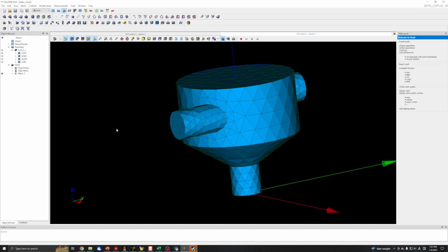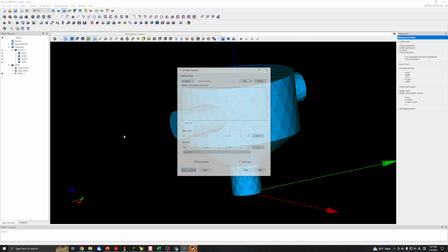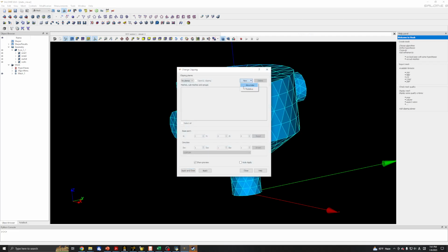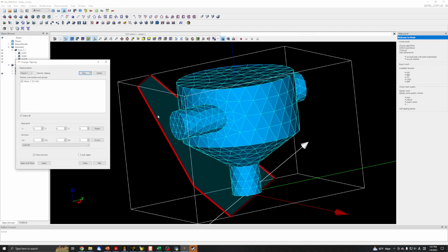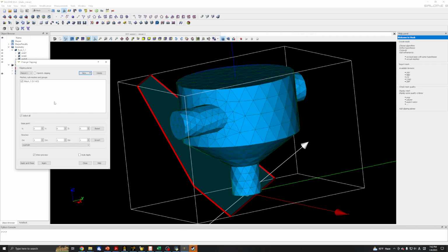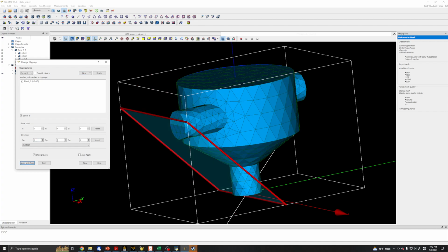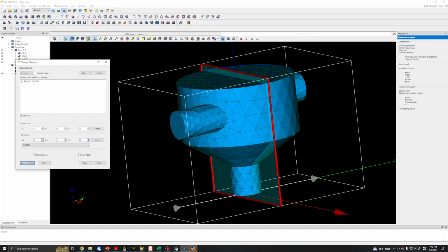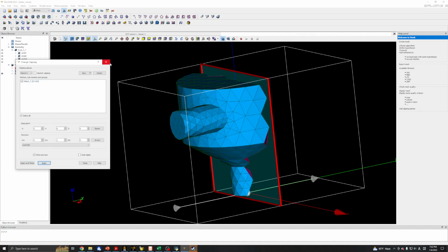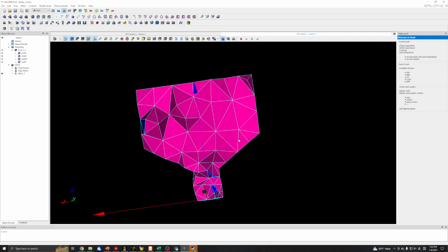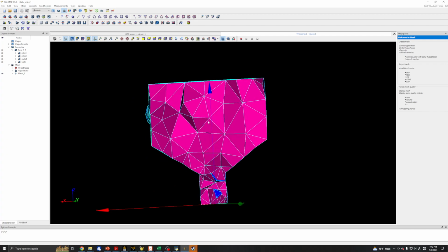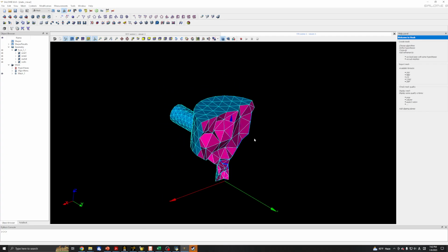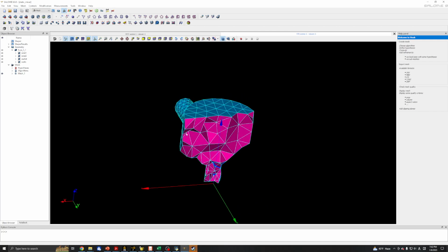First, right click on the main window and choose clipping. Then we can choose new absolute. Now we have our plane through which this mesh will be divided. The direction I want is the y direction, so all we need is to make dx and dz 0 and apply. Oops, it's too big, right? Okay, this is how it should look.